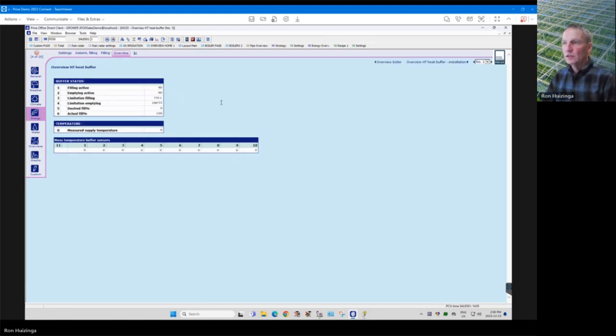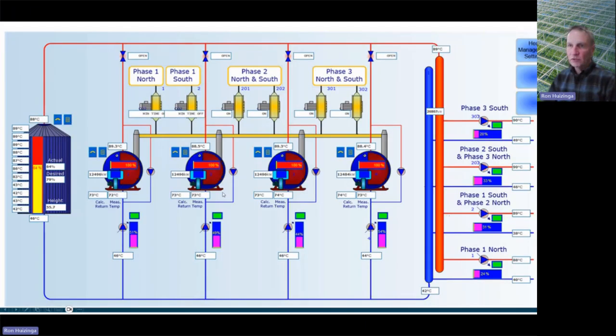So what determines when the tank is empty? Because sometimes the return temperature, if it's not a cold night, then maybe the return from the greenhouse is like 38 or 35 degrees, and maybe on a very cold night, the return temperature into the tank is 45 degrees or so. So the return temperature coming into the tank is going to depend on the return from the greenhouse.